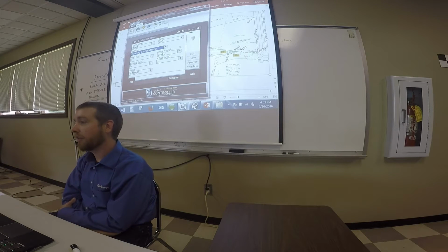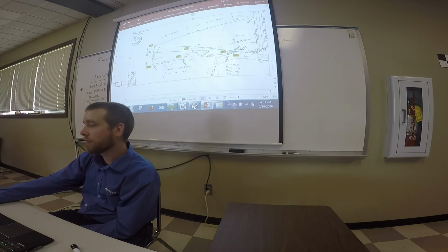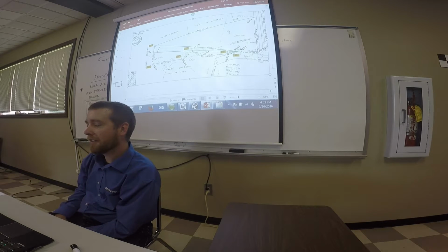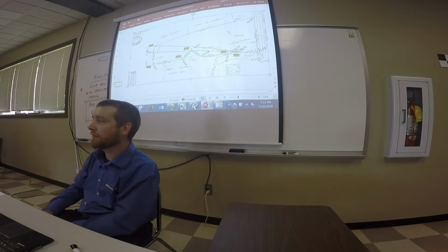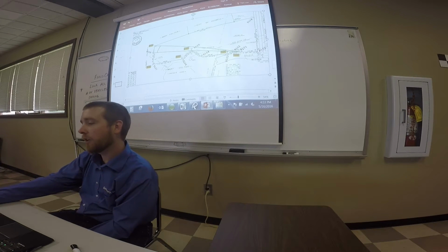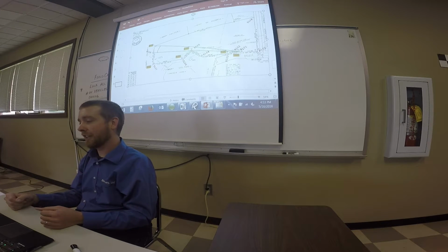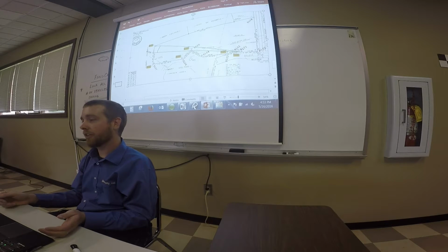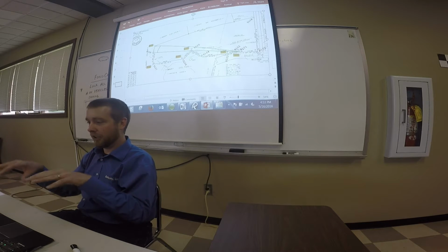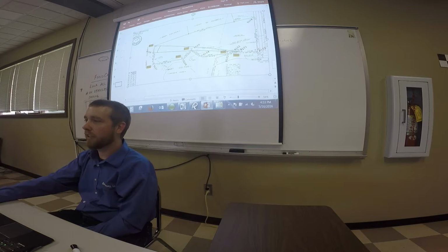Okay. Are there any other questions? Why did you choose point 103 to rotate from and then 845 to rotate to? I just chose two points far across the site. I really could have chosen any points. If you choose numbers 210 and 886, well, that's a very short baseline, and you're going to have error in every shot. Every pin you find is going to be a little bit off from what the previous surveyor said it's going to be. So if it's off a couple of hundredths, by the time you translate and rotate to just that angle, this one over here could be several feet off.